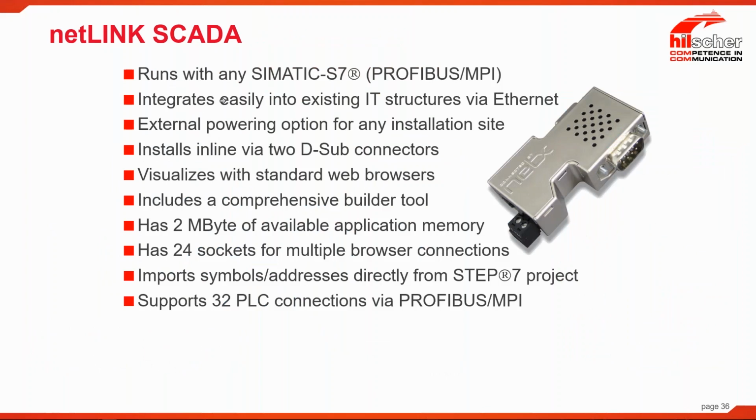So this will run with any older Siemens controller that has an MPI port, and the thing is, it will basically provide SCADA usability, but not as much of it. So for $1,000, there's not a whole lot of memory inside this device, and so you're able to get maybe 10 to 12 pages on this, and no more. But still, it's $1,000, and it gives you some very low-level visualization for it, and it's accessible via any web browser.